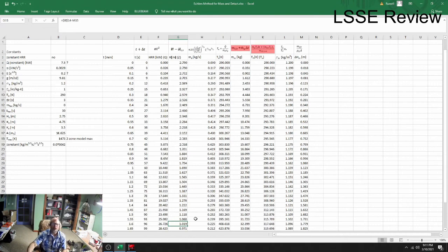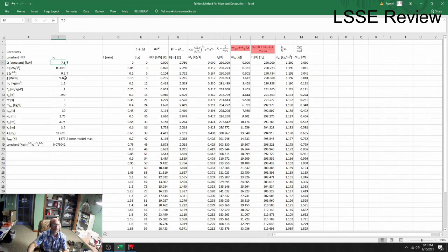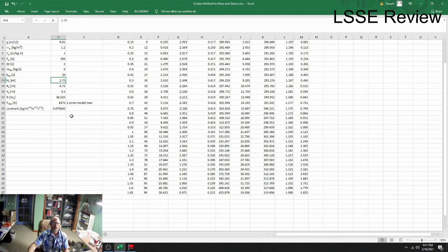So in this case, this particular compartment is fairly small. I just set this up. Your height is going to be about 2.75 meters. So it's a fairly small area. That comes out to be about 8 feet tall ceilings. So in this case, I just wanted to evaluate it. I mean, it'd be pretty fast if it went from 8 feet to 6 feet in the compartment. So in this case, I went down to 1 meter, about 39 inches thereabouts. So you could crawl out.